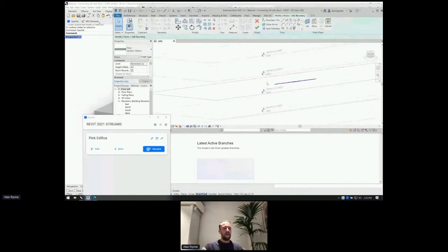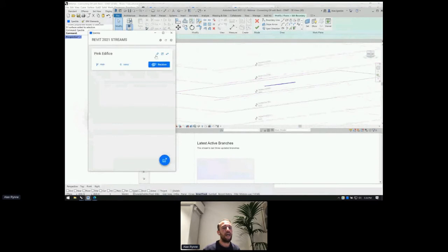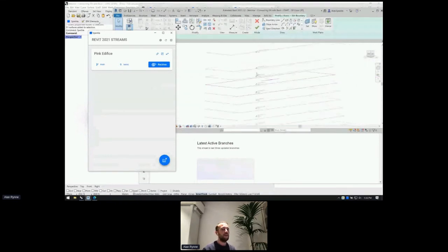This is no longer a surface that you created in Rhino. Once you received it with this Speckle schema attached, we do the hard work of interpreting these elements and converting them to native Revit elements for you. This does have some limitations, specifically, for example, in the case of floors. We do our best to update existing elements as opposed to replacing existing elements, but there are some things that are going to be replaced